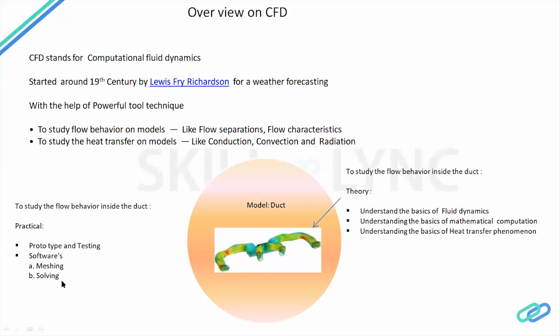Next is solving, where the physics of fluid dynamics comes into the picture. The continuity equation, Navier-Stokes equation, heat transfer, etc. will be part of solving. Before going to solving, we need to prepare the model for the solving. The model, in this sense, is the division of the geometry into the desired shape. So this is like a virtual simulation.